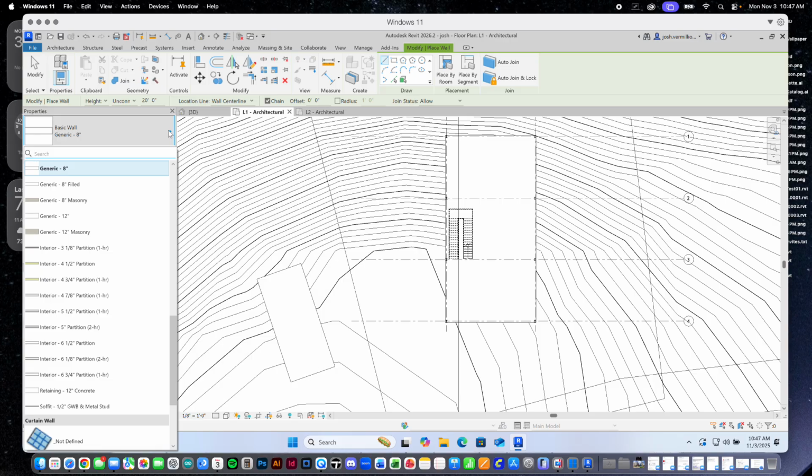So when we look at interior partitions, we think about basically just walls like this or like that, right? Maybe some studs, maybe some chipboard on either side. They don't need to be thick. They just need to be able to, so they don't punch or kick through them. They're not separating inside from outside. They don't have to act thermally, so you don't have to insulate them or anything like that, right? They're really simple, straightforward dudes, right?